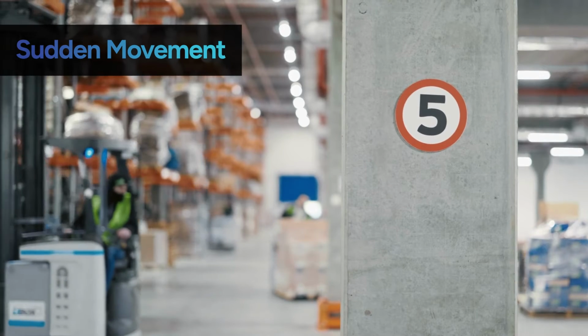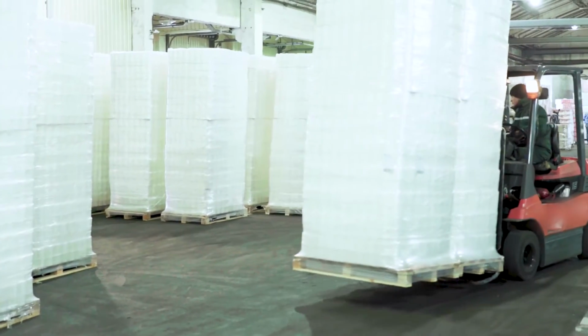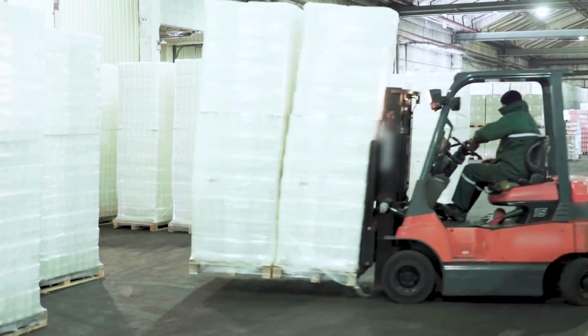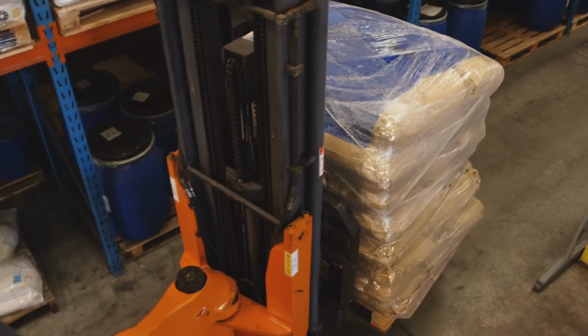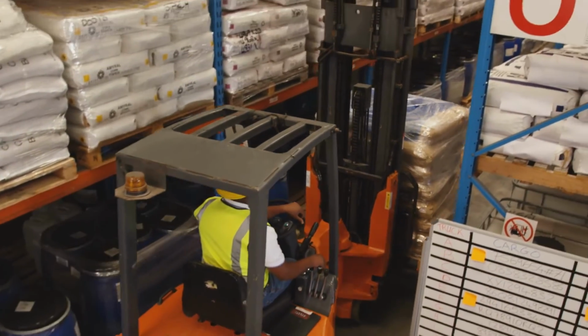When operating a forklift, any sudden movement causes the center of gravity to shift. For example, sudden acceleration or braking can move the center of gravity to the front or back of the stability pyramid, while rapid turning can also shift it to the sides, increasing the risk of a tip over. Smooth, controlled movements help to maintain a balanced center of gravity and minimize this risk.